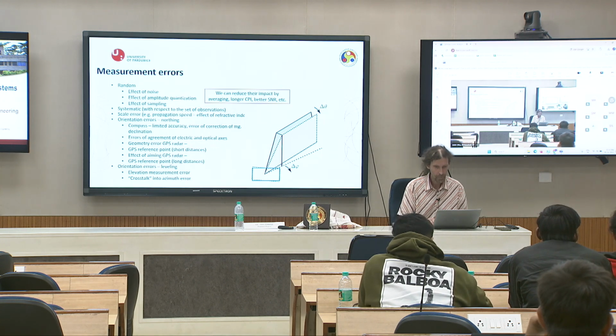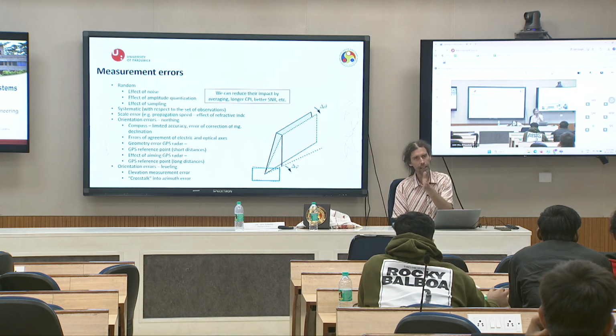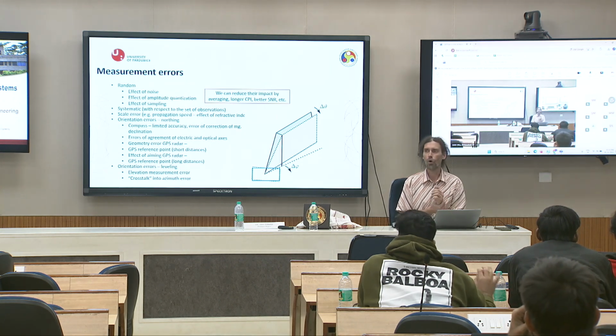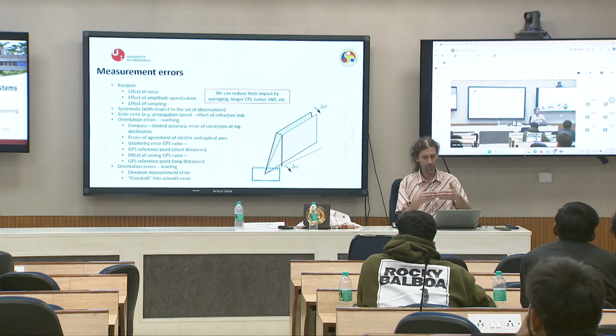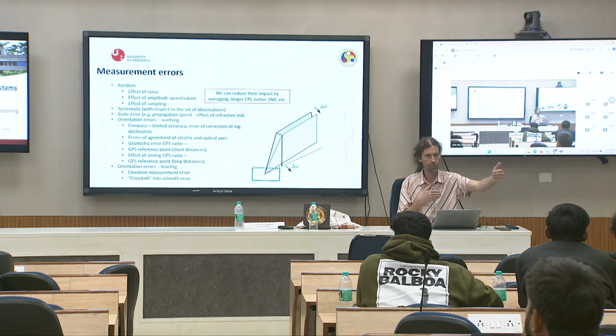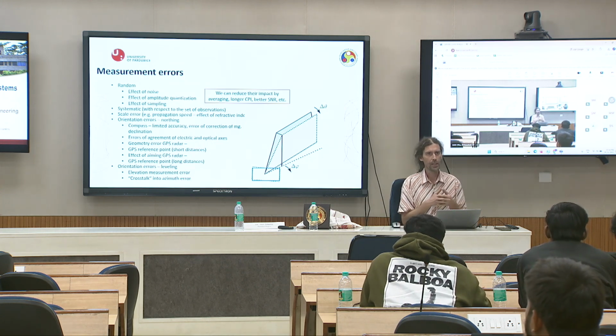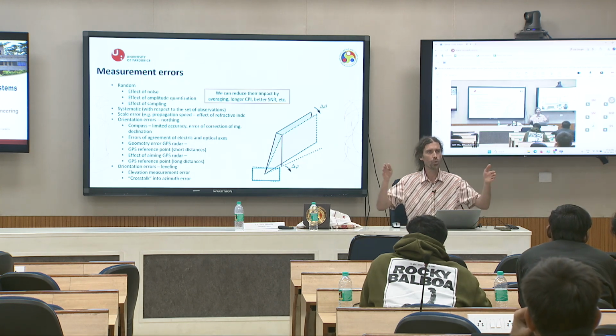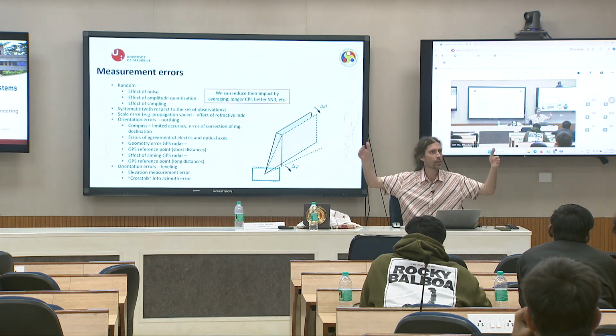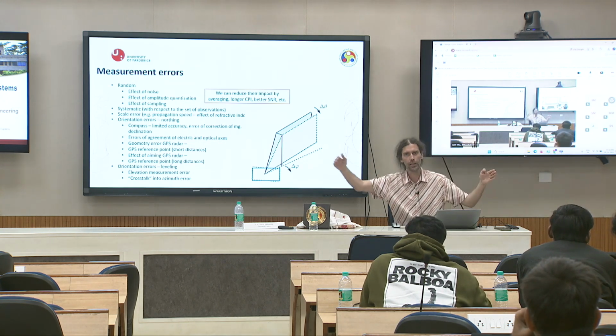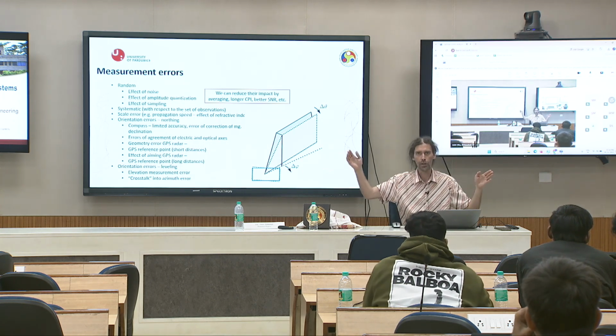What is CPI? It is the coherent processing interval. Until now I showed you that we transmit one pulse, receive, one pulse, receive, but this causes poor resolution in Doppler. I need better, so I make integration through many and many pulses, not one pulse, but through an area of 100, 1000 pulses. Longer integration time improves it.